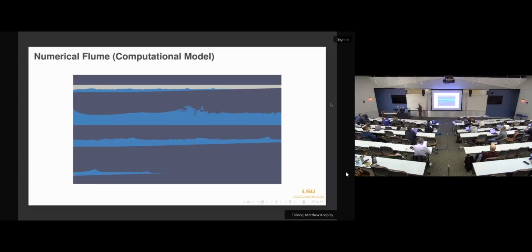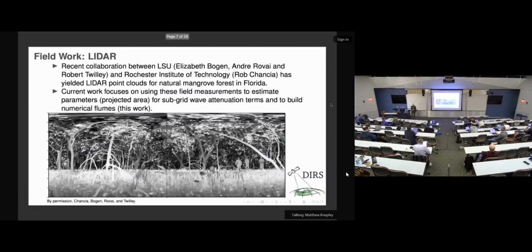So it's a particular range of waves that instead of forming a nice curl and plunging, the tops break apart and they spill. It's very turbulent. And this is a part of how those waves are going to dissipate as they're moving inshore. So this is something that you would understand with a physical flume, and it's something that we can predict with a computational flume. So what we're trying to do is reproduce some of that success in the context of vegetation.